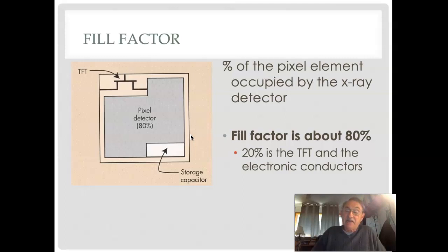So the higher the fill factor, the better the detective quantum efficiency. Can you see how that works? Because I've got more area to capture the signal, and so I have less signal that I might need to give it.